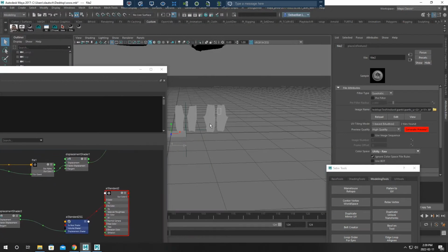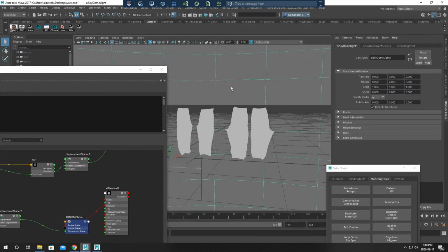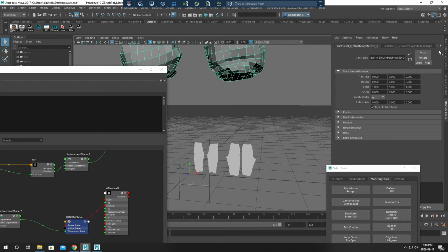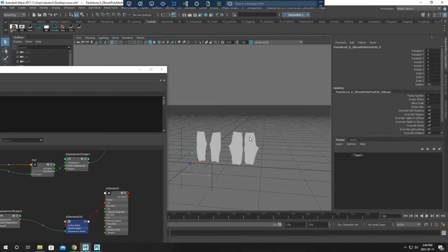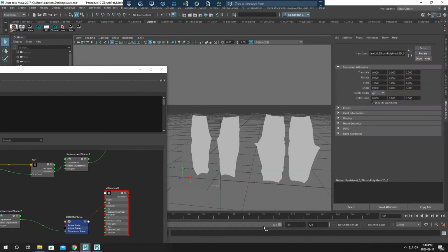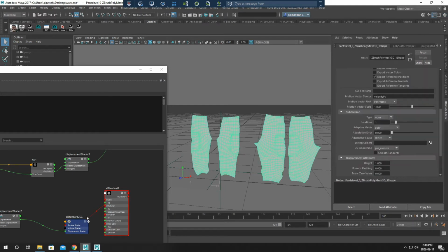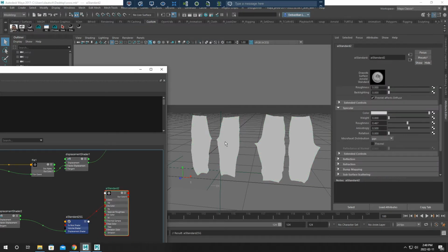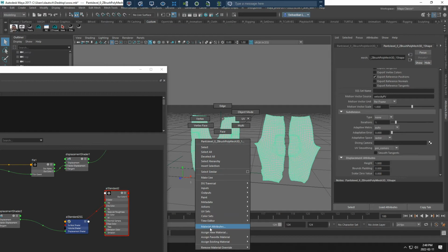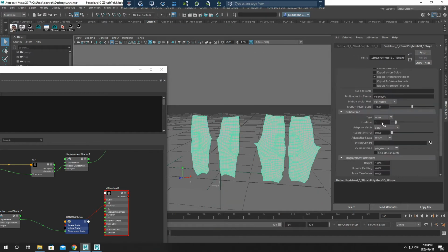And first of all, I'm gonna drag and drop this material on this here, and I'm gonna check it here. These pens I'm gonna put in a separate layer and hide it. And let's check if the material is plugged in. Okay, material is plugged in. No, it's not. Assign. Okay. Material attributes, aiStandard, everything's in. Let's select the model and go to Catmull Clark and hit 8, 5.